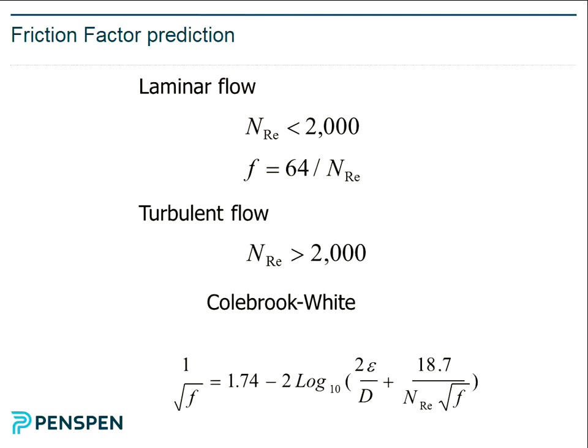And for very high Reynolds numbers, you can see the friction factor ceases to be a function of Reynolds number. So this is called laminar, this is called transitional, and this is called completely turbulent flow up here. Any questions on that one? I don't know if you can see it, but I think you get the general principle.